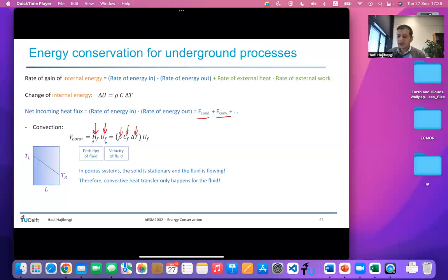Now, what I would like to do is go to a 1D porous media system and write down the conservation of energy for that and find out what the temperature distribution in my system is, depending on how strong conduction is, how strong convection is. And so I would write a 1D conduction convection equation for the porous samples we have in many places in reality, and that would also help us understand what the temperature distribution in the system is.